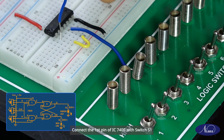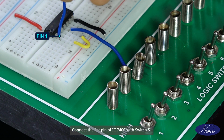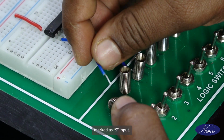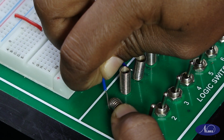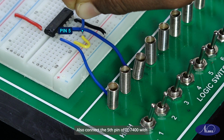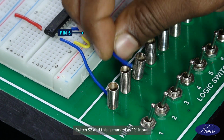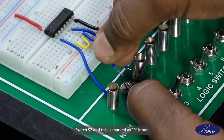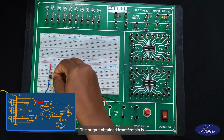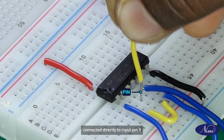Connect the first pin of IC 7400 with switch S1 located in the trainer kit, and this is marked as S input. Also, connect the 5th pin of IC 7400 with switch S2, and this is marked as R input. The output obtained from the third pin is connected directly to input pin 9.